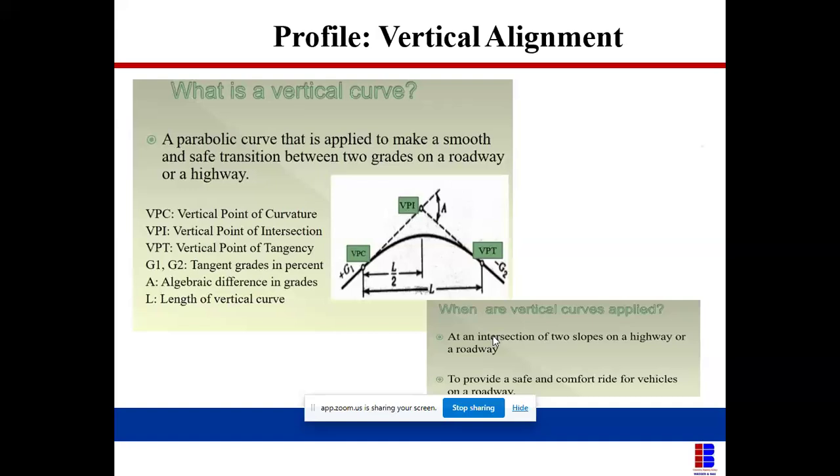Like you said, most things depend on the design speed of the road. The design speed of the road is one parameter that determines a lot of factors. Yes, minimum sight distance is about 150 for about 80 kilometers per hour. So it depends on what speed you are designing for, but it's in the highway manual, and we'll share it after the class. All right, thank you. Noted.